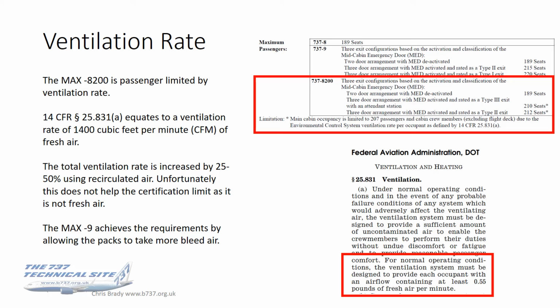If you do the maths, if you reverse engineer your 207, it comes out to 1400 cubic feet per minute of fresh air. And this is, I'm sure you'll agree, a heck of a lot. And again, in these times of COVID, it's probably worth some comfort to people that there is such a high volume of fresh air required every minute. I mean, 1400 cubic feet is a lot of air. And in fact, the air in the 737 is actually completely changed every couple of minutes.